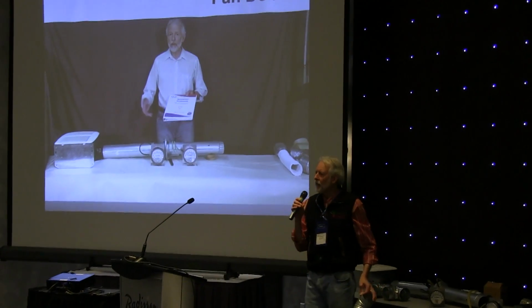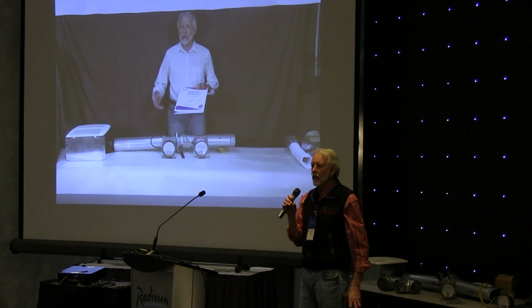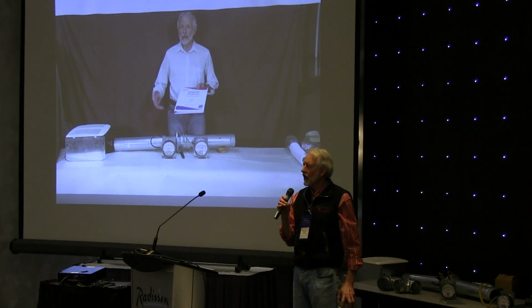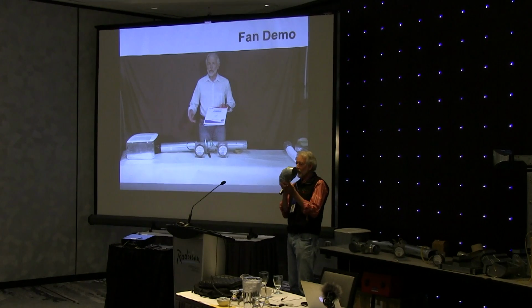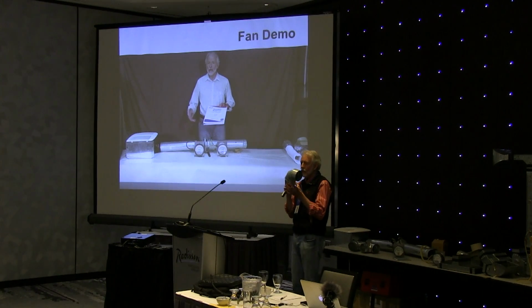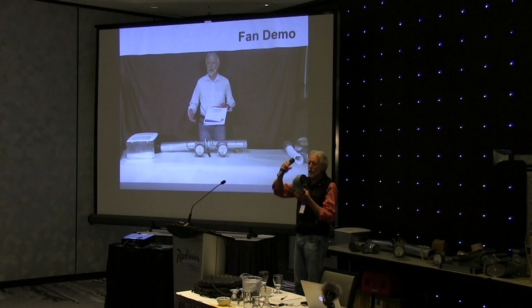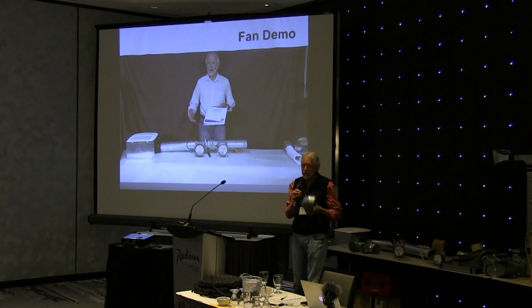The question came up, does it matter whether I push air through or pull air through a duct? Does it make any difference? I won't get into the physics behind it, but the answer is an absolute, unequivocal no. If I'm pushing air through this duct, it's a 4-inch elbow, and whether I pull air through this duct, the restriction imposed by this duct at that air volume will be unaffected, whether the fan is here pulling or the fan is here pushing, it doesn't care.